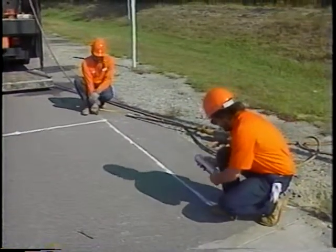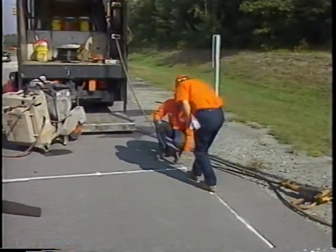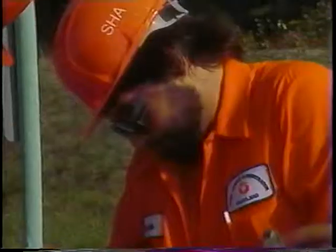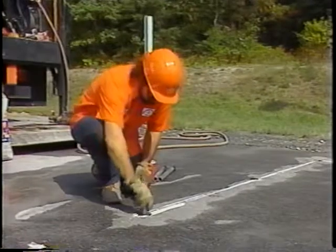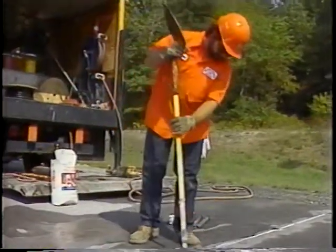After securing the work zone and marking the detection area, use a magnetic field analyzer at each marked probe location. This verifies that the area is free of any elements that would degrade the detector's performance. Next, drill holes with a diameter that is 1/8 inch larger than the diameter of the sensing probes or the PVC pipe if lining the holes. It is imperative that the microloop or magnetometer probe should be mounted in a stable, vertical position. Lining the hole with PVC pipe ensures that the probe will remain vertical if the hole walls collapse. The required depth of the hole should be defined on the construction plans.